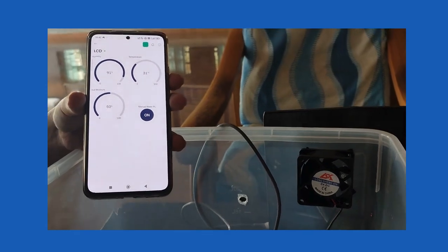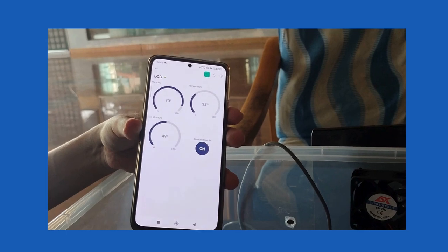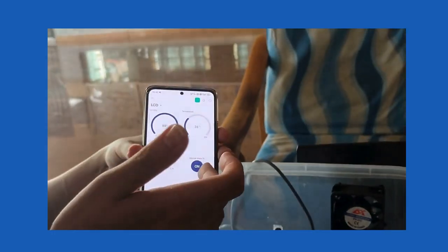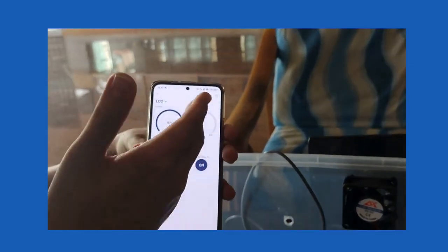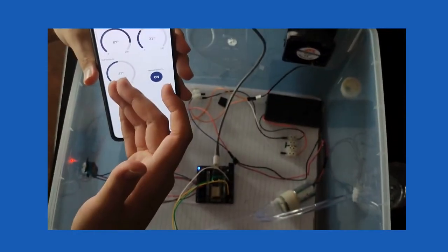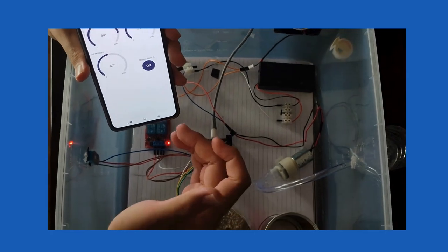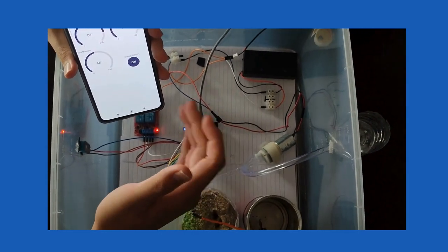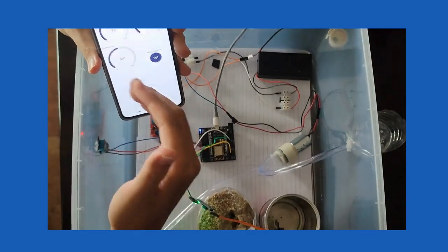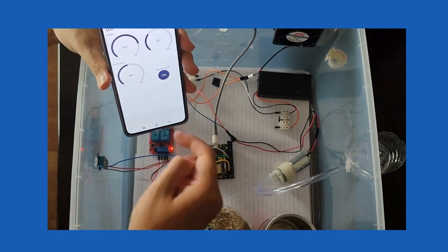As you can see, we also have one manual water button here. You can see this is in on mode. When it's in off mode, that means even though the sensor reaches 32 degrees Celsius, it won't happen, or if the soil is less than 20%, it won't turn on the pump either, because we want our farmers to sometimes use this manual mode for some emergency or critical conditions.